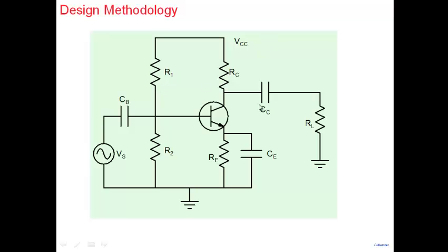Now, of course, there is a popular design methodology among students: let me put some values here. Let me put R1 10K, 20K, some value. Let's just throw in some value, and then you go ahead and simulate it. It's not going to match what you're looking for. Maybe if you're lucky, 1 or 2 specs may match. If it's not going to match, let me increase R1, let me decrease R2, and you iterate between guess and simulation, right?